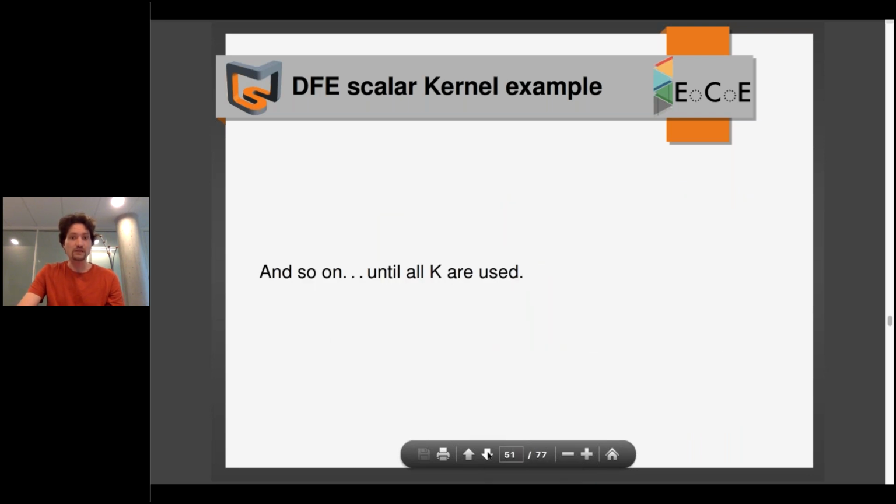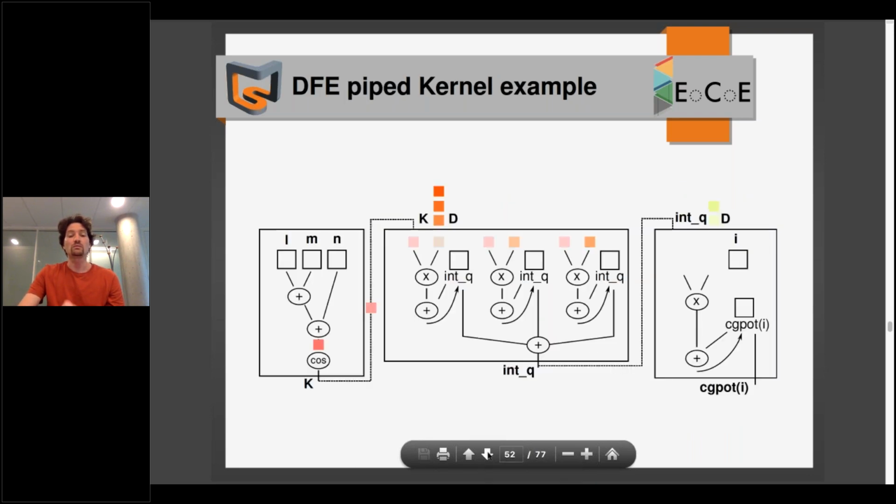So the good thing with FPGA is that now we can implement our own vector units. As we are deciding the hardware, instead of treating one atom at once in this part, we can treat them 3 by 3. It will put more pressure on the memory bus to bring data here, but then I will be able to compute 3 by 3.